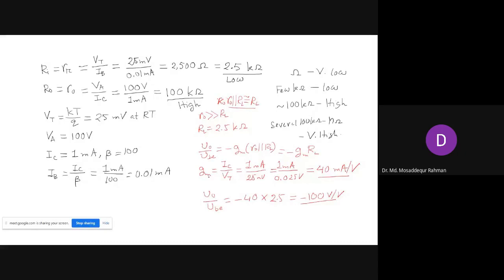Now, to get high gain, you need a high value of IC. Of course, increasing IC will demand more power, and there will also be higher power loss, because you have I squared R loss in the circuit. The higher the R, the higher the power loss. Also, with an increase in IC, your r pi will decrease, because IB increases, so there will also be loss at the input side. So there's some trade-off you need to make, or you can modify the circuit.